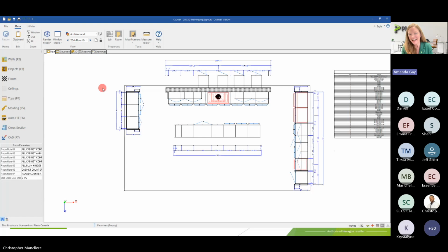Perfect. Thank you. Next question, can dimension styles be set up as annotative so numbers show up at a consistent height in paper space no matter what scale is being used? Another good one. Currently, no. It will really just change the scale as a whole, but not cover a specific defined space. So I would say that's an idea that we could submit, but right now it will just basically be scaled and just basically cover just the length of the text itself and not actually change the spacing of the text. Perfect, thank you.